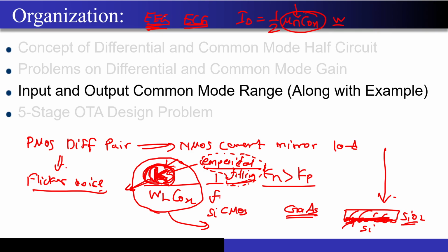Now these signals are very weak, correct? And if you don't want to decrease the SNR by introducing a lot of noise, you have to use a PMOS differential pair to make sure that you do not introduce a lot of noise in the signals. Now why does it matter so much?